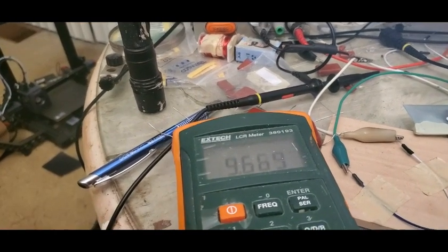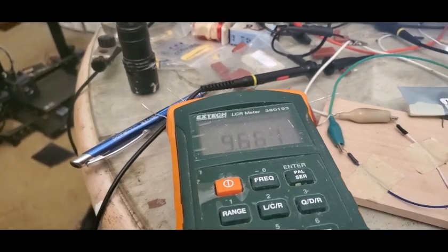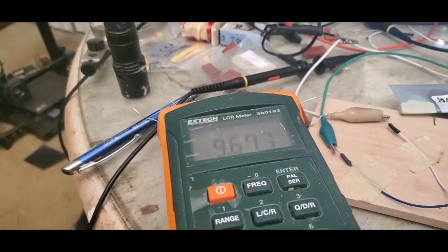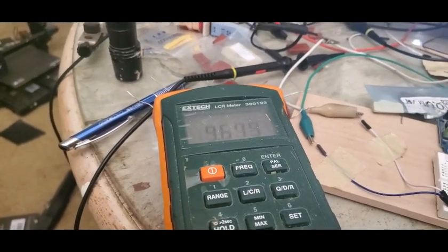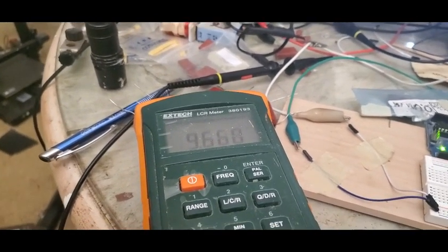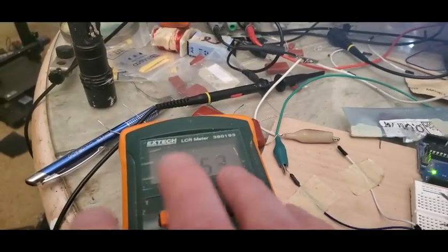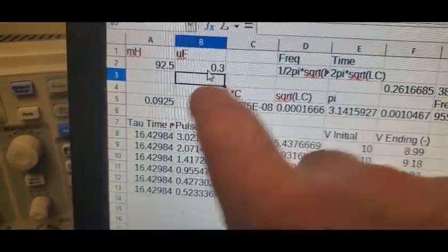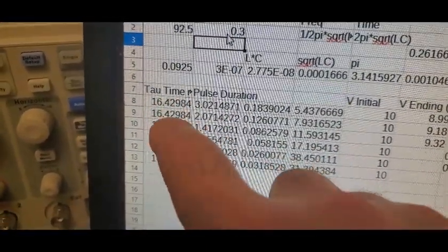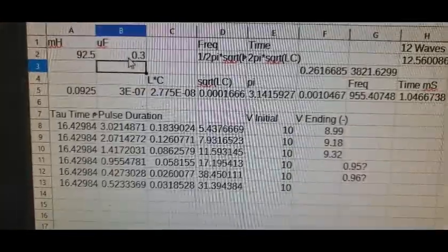And that's why you saw a great improvement from 10 to 1, and then 1 to 0.1, it didn't really do anything. It didn't get much better, it didn't get much worse. And then going past that, it was just falling off the edge of a cliff, getting worse. And that's because the resistance from proximity effect is increasing, and hence this tau time is no longer constant. The tau time is decreasing, and all of this changes.